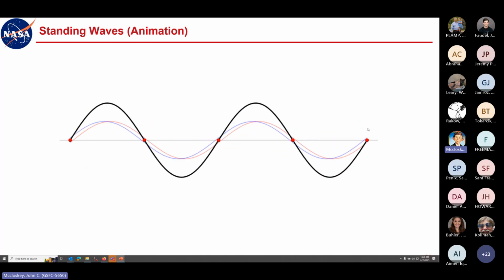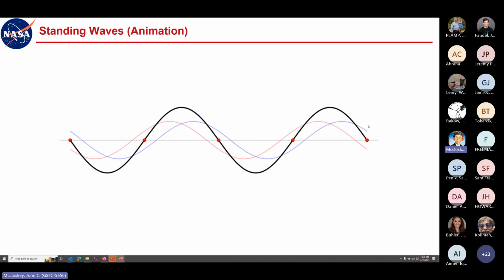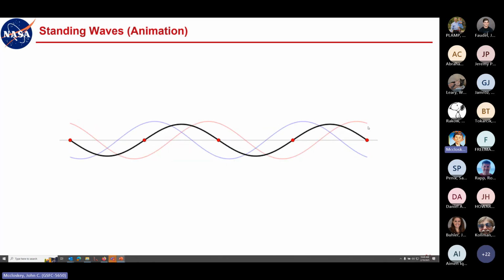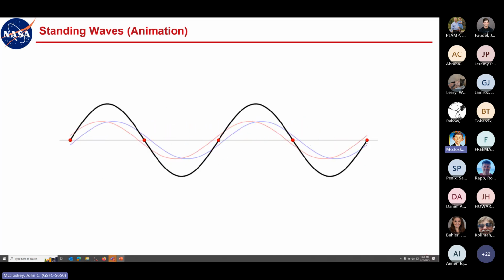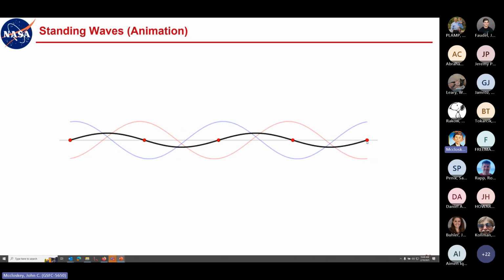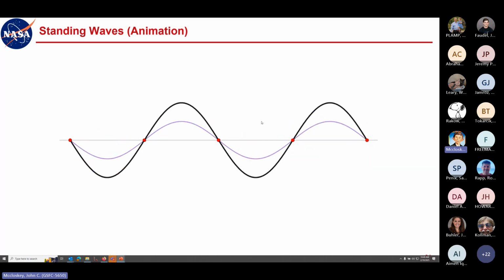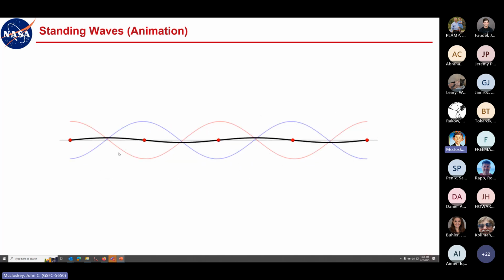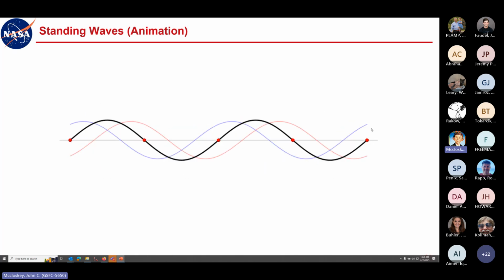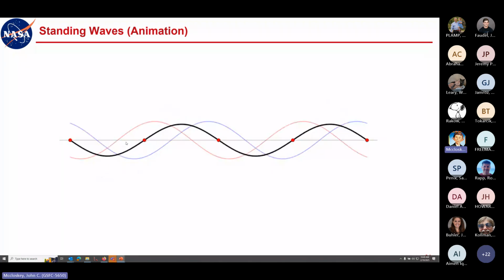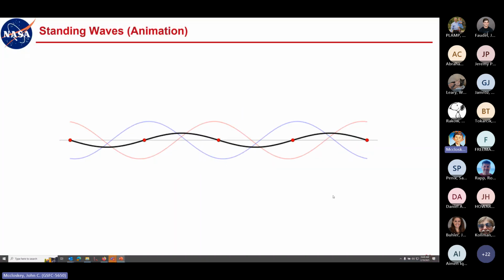So the reflected wave, the red wave, is going to be the negative of the blue signal at that point to basically give you a net voltage of zero at the termination. And so then that reflected wave starts heading back in the other direction, and the combination of it gives you the black trace, which shows standing waves. You have patterns of peaks and nulls along the cable.